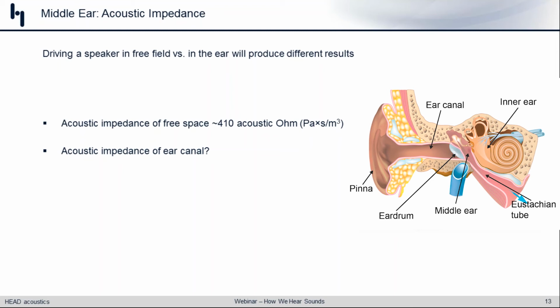Now you take that headphone and put it up over an ear, and all of a sudden, the acoustic impedance inside this relatively small closed cavity, right? You have the pinna itself, the concha bowl, or the cavum concha, the ear canal, which presents a vastly different acoustic environment than what you saw in free space. And the response of that headphone transducer is therefore going to differ from what we saw in free space. Now, once again, why do we bring this up?